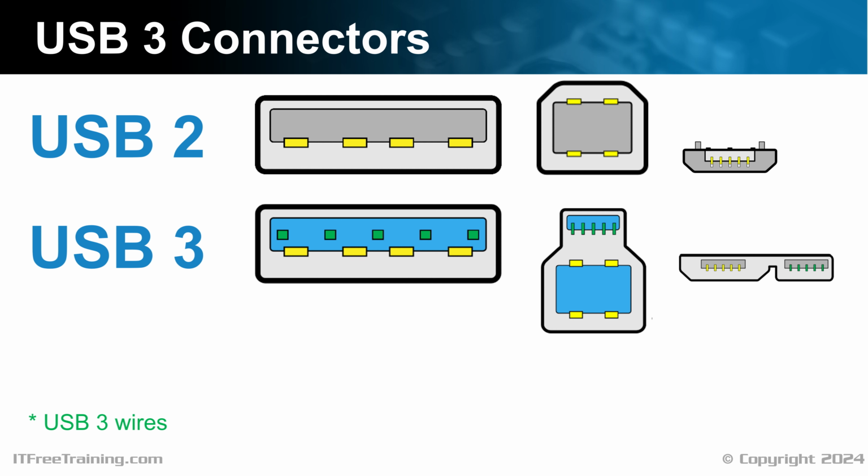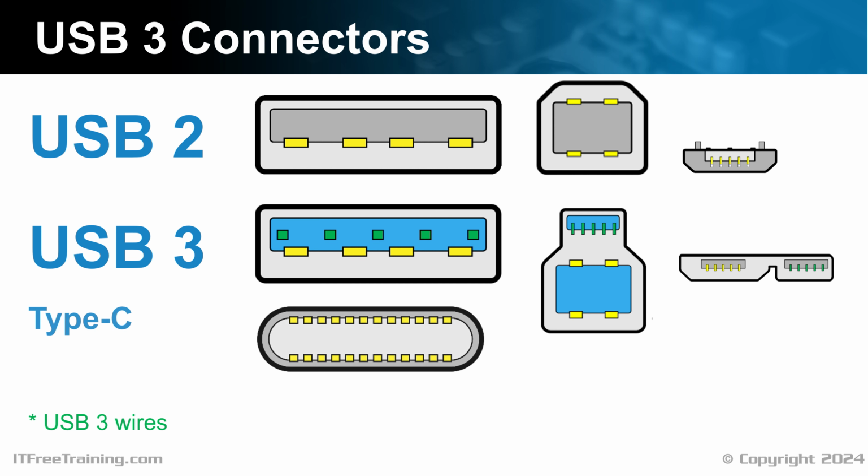After the initial release of USB 3, a new connector was released called the Type-C connector. This connector does not have a USB 2 version. However, it does still have the USB 2 wires in it for backwards compatibility. Thus, the cable supports USB 3 and USB 2. As before, there are a number of pins that are dedicated to USB 3. You may notice that there are 8 pins for USB 3, whereas before 5 were added. The previous 5 consisted of 4 data wires and 1 ground wire. Thus, 4 data wires in the previous connectors and 8 data wires in the Type-C.